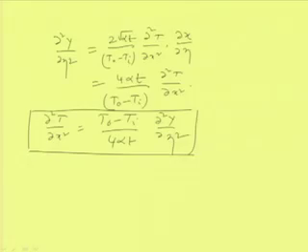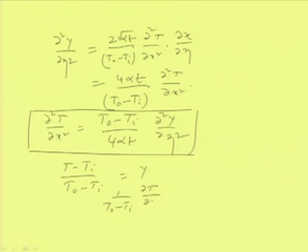Then there is another term, that is ∂T/∂t. We write (T − Ti)/(To − Ti) = y. So, 1/(To − Ti) × ∂T/∂t = ∂y/∂t, but we are not interested only in ∂y/∂t, we are interested in ∂y/∂η. So, this will be equal to ∂y/∂η × ∂η/∂t.